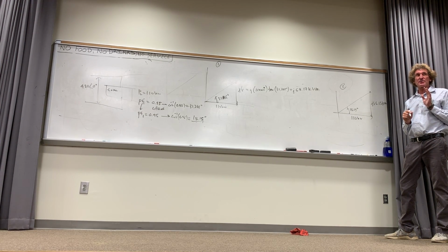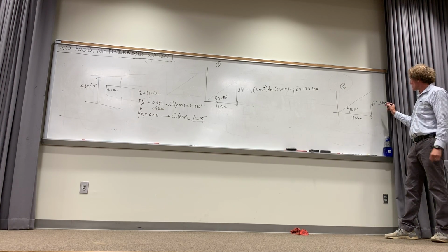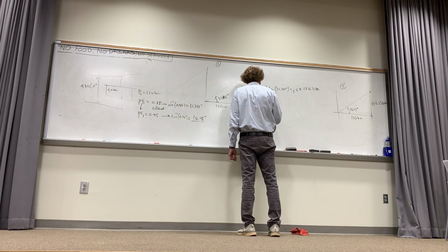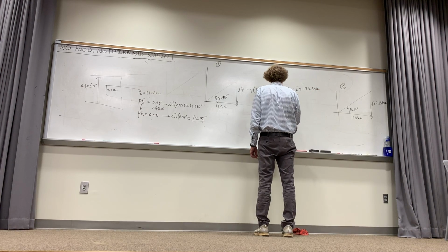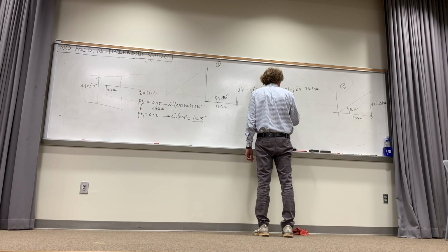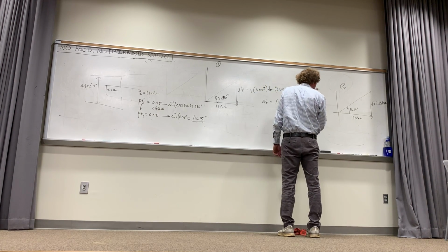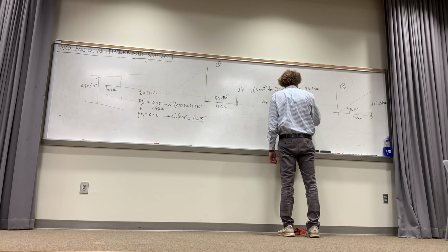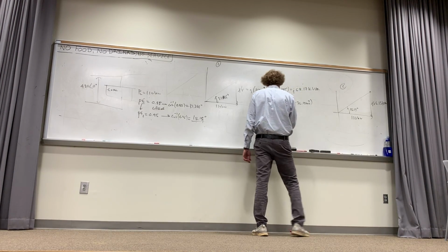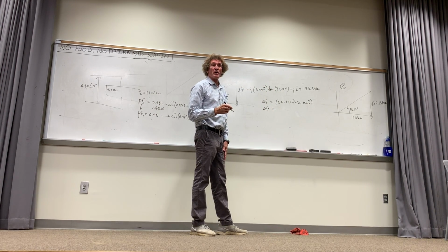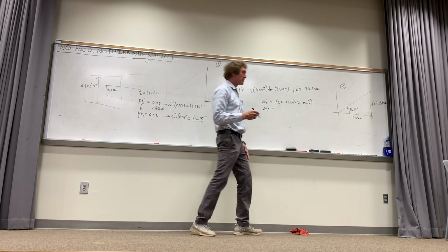Ideally, you would want that power factor to be 1, or the aim, you don't want any reactive power. But we're getting it closer, so this is where we're going. It's reduced by a total of what? What is the delta Q? That's equal to 68.17 times 10 to the third minus 36.15 times 10 to the third. What's the change in the reactive power? About 32. What is it exactly? 32.02. Thank you.